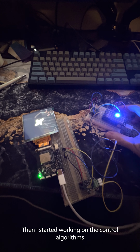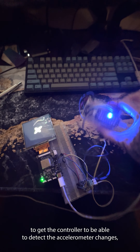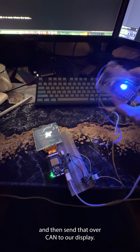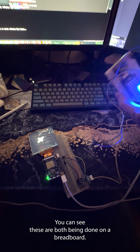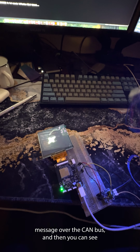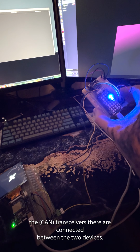Then I started working on the control algorithms to get the controller to be able to detect the accelerometer changes and then send that over CAN to our display. And you can see these are both being done on a breadboard. Each movement is a single message over the CAN bus, and you can see the transceivers there connected between the two devices.